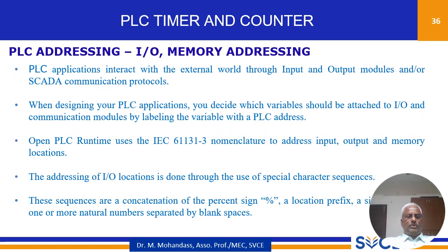So next one is the PLC addressing. First one is the input output memory addressing. Addressing is very important in PLC because we need to define what has to be taken from the memory, what has to be stored to the memory, what has to be taken from the memory to process and give the output, and what has to be received from the data acquisition card or the sensors and stored in the memory.